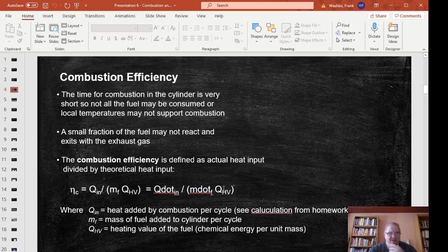So part of that is combustion chamber design. If you look at the engines that you tear down, you'll see that the pistons look different. Sometimes they're just flat, but sometimes they have some contour or shape to the surface, because that's part of the combustion chamber. You will see that all the combustion chambers in the head where the valves are look different from one engine to the other, because that's the shape of the combustion chamber, and that's going to determine how the